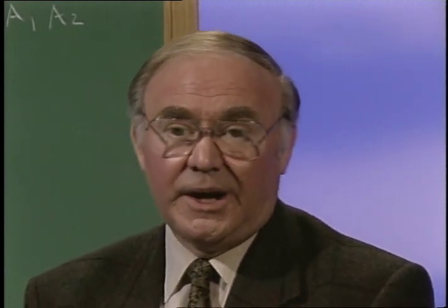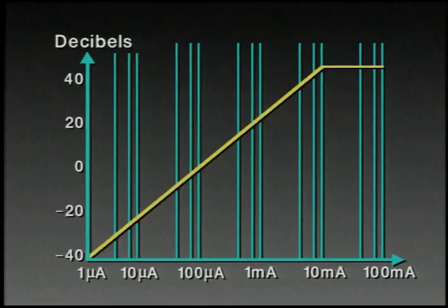Now there's a subtle sort of caveat to that. Clearly, if beta is finite, then not all of the tail current, 2IY, appears at the collector. So there is an alpha error, and it may sound like a fine distinction to say that there's an alpha error but no beta error. But what I want to show is the following. If we were to make an amplifier using this principle and plot its gain as a function of the tail current shown along the horizontal axis here, we'd find that it was an exact function of the tail current right up to the beta point.